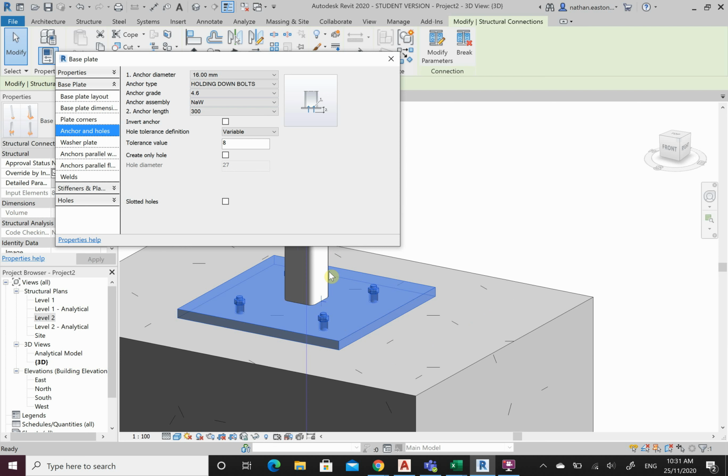When you've got the thread sitting through, we have to try to locate the plate and column on top of it. If we have to move them, they're not very good for that aspect. Alright, in tension, fantastic. When they have to move laterally, they tend to snap. And then we can change the diameter of the hold down bolts as well. We can change the length of how far it's sitting down here.